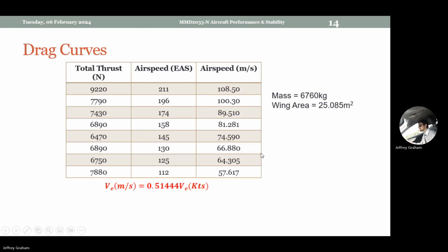Right. Here's our scenario then. So we took our aircraft to an altitude. Doesn't particularly matter where, as long as it's fixed. We took a thrust value when it's trimmed and not accelerating, and the airspeed this occurred at. You can see we slowed the aircraft down, trimmed it back out, took a new reading, slowed down, a third reading, then a fourth, and so on.